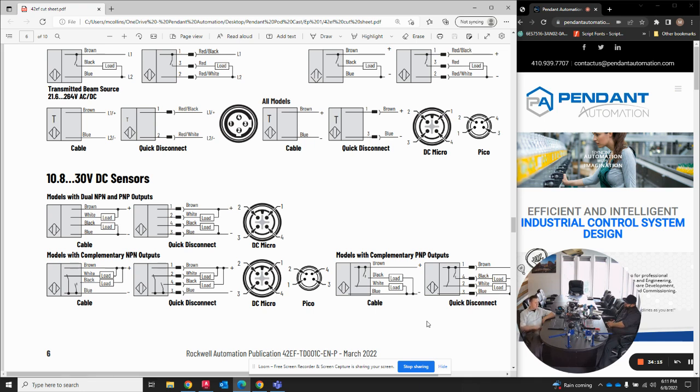However, a lot of manufacturers use NPN because they can ground the chassis and then they can pick that up everywhere that they go. In fact, that was the problem at Macy's with that extendable conveyor. We were trying to troubleshoot how they were getting the signal back to the circuit board, and they ran it through the chassis. I'd never seen that before, nor do I think that's good practice. But hey, I guess if you save one wire, that's as good as saving 10 wires or something like that. I would call that a shoddy way to do it.